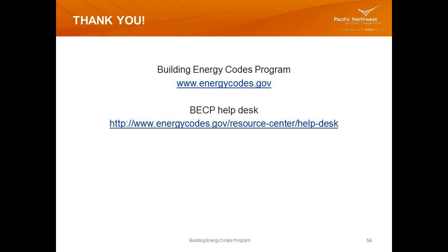That 90.1 standard version depends on what version of the IECC. So, for example, 2012 IECC references ASHRAE 90.1 2010, and 2015 IECC references ASHRAE 90.1 standard 2013. So again, those are direct references. And unless the state or jurisdiction has amended out that you can't use 90.1, you can use it.